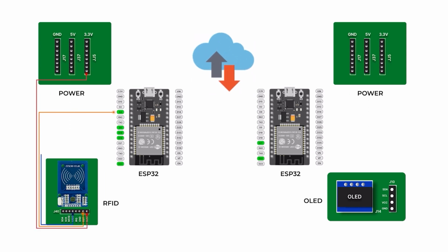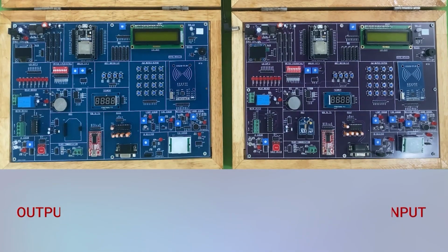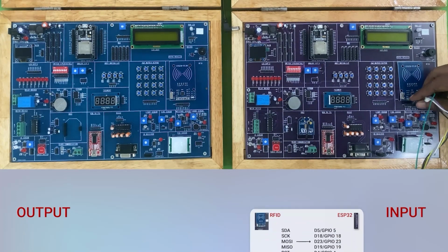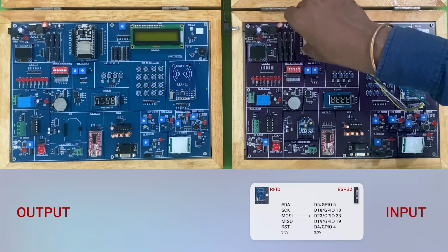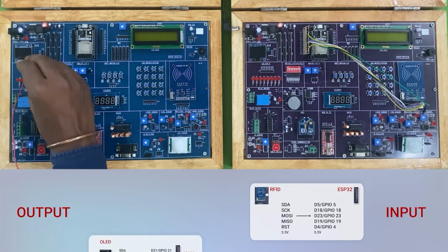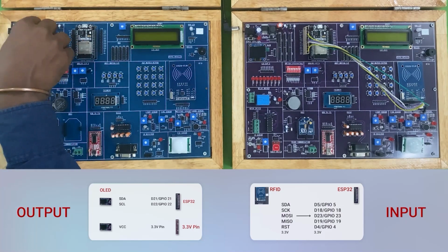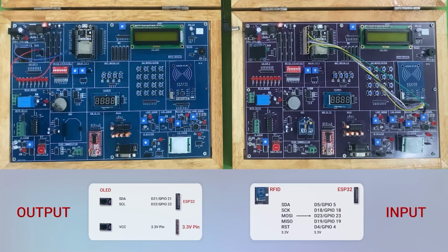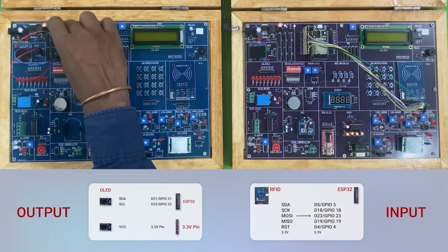Here the circuit diagram shows the actual wire connections being used. Connect the selected input, that is RFID, to the 3.3 volts power pin and the input pin to the GPIO 5 and 4 pin for in one kit. Connect the selected output OLED to the 3.3 volts pin. An SDA pin to the GPIO 21 pin, SCL to GPIO 22 in another IoT kit.